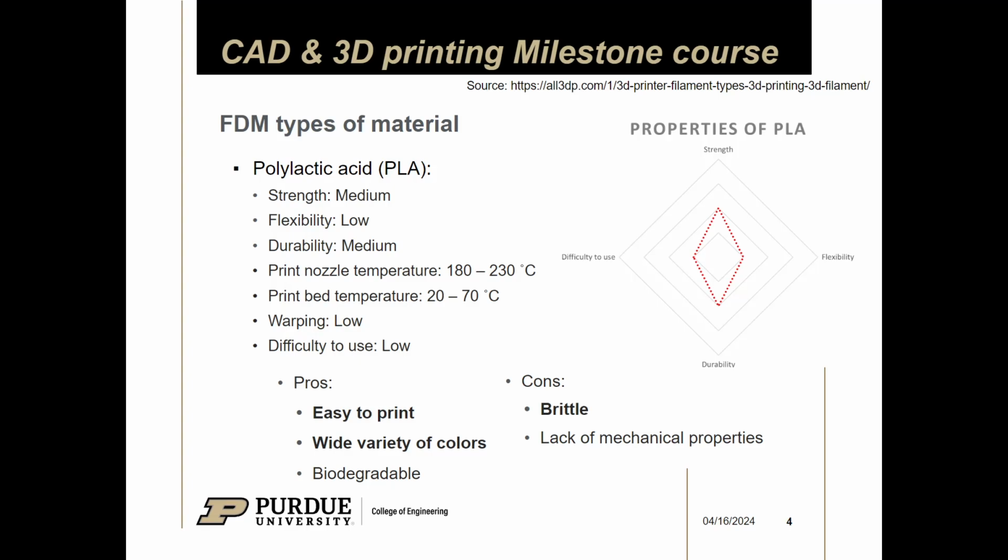It's really nice to use just because it likes to print very easily because it melts at really low temperatures. And it also means that you usually don't need to run very high bed temperatures either. Back in the day, a lot of printers didn't come with heated beds, and that's why PLA became such a great option just because it was so forgiving. And people like it today because it actually cools very well. So when you're printing very fast, you can just blow a ton of air at it and it'll cool down. It doesn't really like to warp very much. So that's often why it's a very popular material.